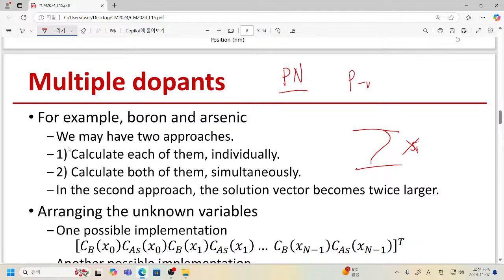First, fabricate a p-well, with relatively low doping of your p-type dopants. After that, you introduce n plus implantation on the p-well. Then you will have an n plus p junction. Quite similarly, you may have an n-well, a region with relatively lowly doped n-type dopants. After that, you implant your p plus doping onto it, so you will have different polarities.